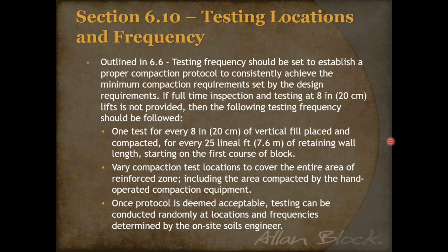And so the contractor would have to go out there, talk to a third-party tester and say, okay, how often are you going to test this? And they would leave it up to the experience there, so the third-party tester, the geotech or on-site engineer would say, yep, I'm going to be out here. I'm going to do it by volume, or I might do it by lift.